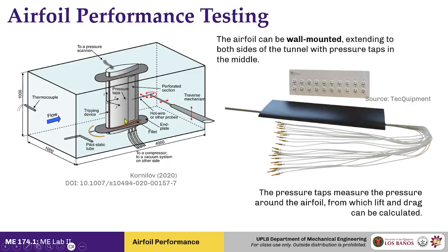The difficulty with this setup though is that those taps, the insertion of the pressure tubing, also can be a bit complex and expensive. So even though there is a mountain of data that you can look at through the pressure distribution alone, you might not have the capacity to actually manufacture this kind of pressure tap airfoil.